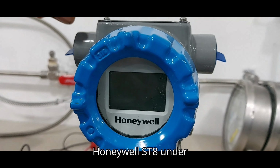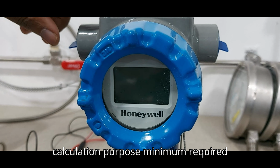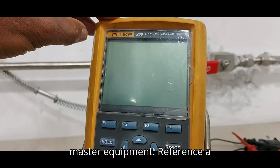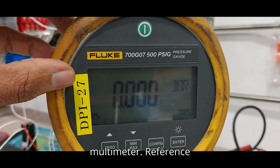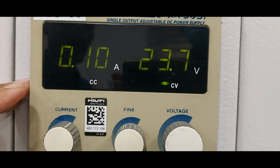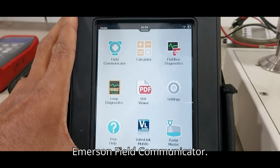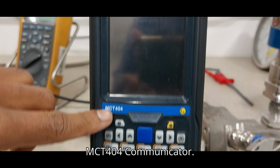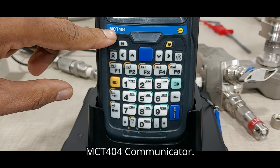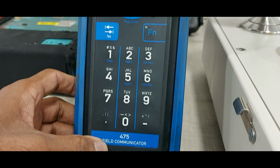Honeywell ST800 calibration purpose, minimum required master equipment: reference multimeter, reference pressure gauge, 24 volt power supply, field communicator, Honeywell MCT404 communicator, next field communicator 475.